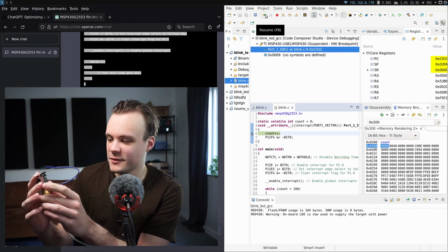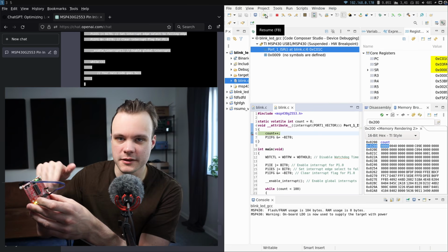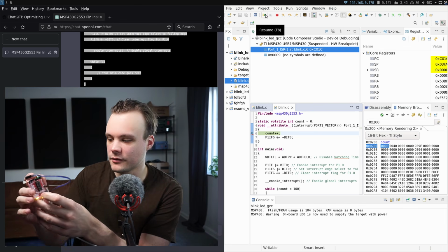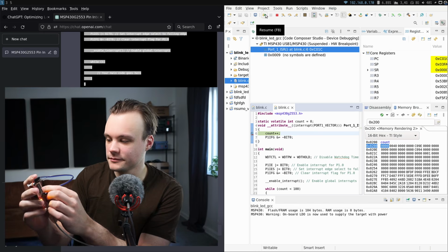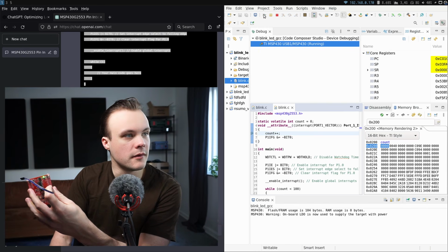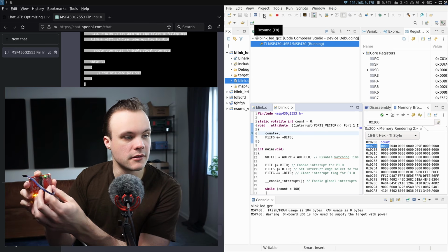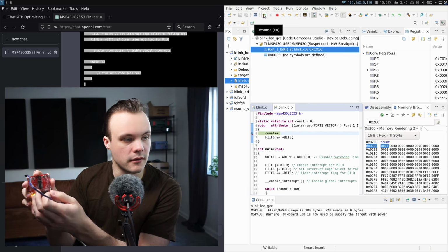Now it triggered immediately here, since when I connect the line, the voltage may wiggle a little, and that may cause an interrupt, even though I haven't actually disconnected the wire yet. But if I resume, it no longer keeps on triggering the interrupt, but if I disconnected it now, it should trigger the interrupt, and it does.